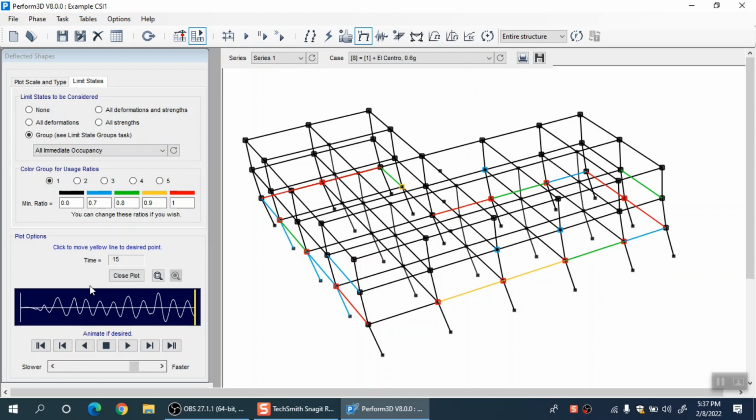You can observe here that in many of the beams, the steel is beyond that 50% level. Let us say the LS level you set equal to epsilon y of steel bars, and if a certain beam crosses that LS level, it means that beam has yielded already.